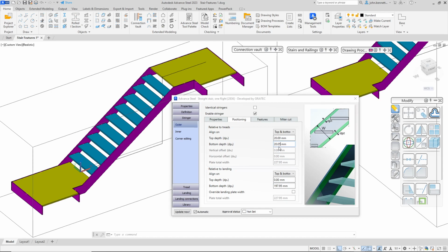So either by making a small change in there, you could round it up to a figure down in here. So this would automatically adjust in this cell. So you would have to work out what you needed to do in order to get to a suitable size that you may require as the user. So typically the plate sizes would come from a standard size flat rolled plate size. So by that I mean a section that can be bought and is pre-rolled in a mill.